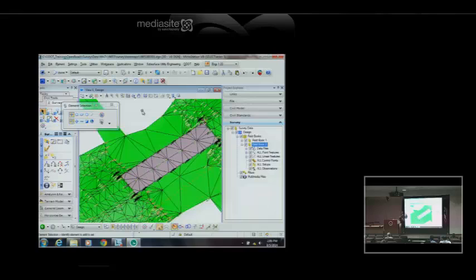Okay. Kevin, have you cut profile? You can't pick more than one terrain model, right? It's just one terrain model. That's what I thought. So I'm just going to have to pick the topo terrain model, and you're just going to see it go down like that. Now, when I make my proposed profile, I can do that, obviously. Go across there.